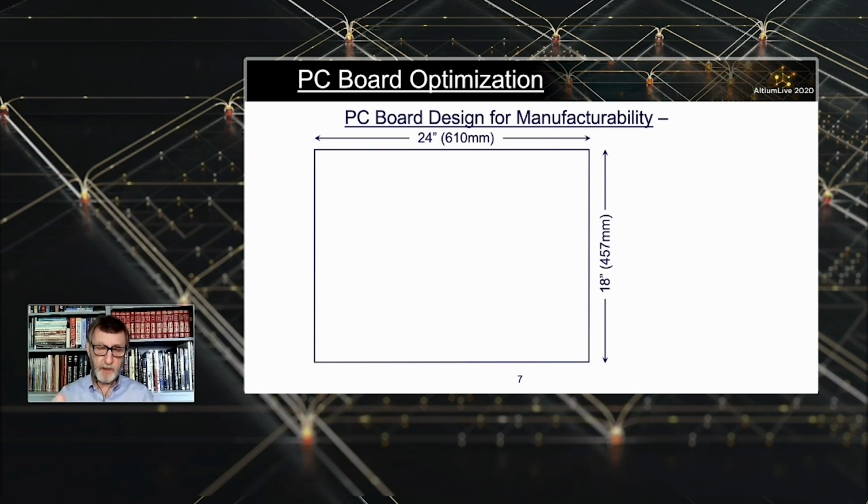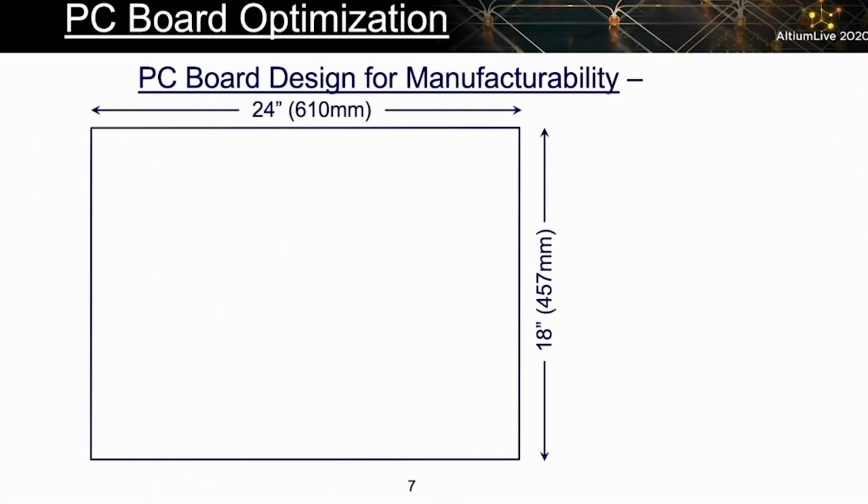We know how big our box is going to be in that equipment bay. And based on the box size and the area we have inside, we know that the circuit boards that are going to plug into the backplane can be anywhere from 5 to 7 inches wide and can be anywhere from 11 to 13 inches long. He said, I recently found out that fabricators build 18 by 24 panels. And so based on that, I thought, oh, perfect. Let's pick a board size that maximizes yield in this 18 by 24 panel. So I made the boards 6 by 12 to fit into this 18 by 24 panel.